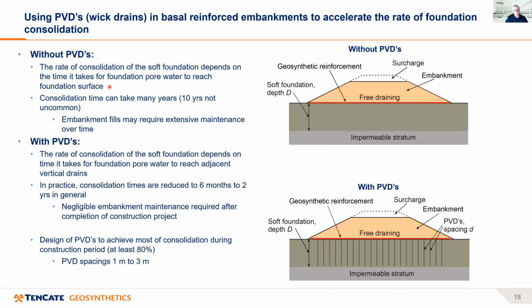So without wick drains, we have this particular case shown in the upper right, where the embankment loading plus surcharge drives the pore water out of the soft foundation and drains across at the surface. And consolidation time here in this case can take many years, with 10 years not uncommon. And of course, over this 10-year period, some of these embankments may require extensive maintenance.